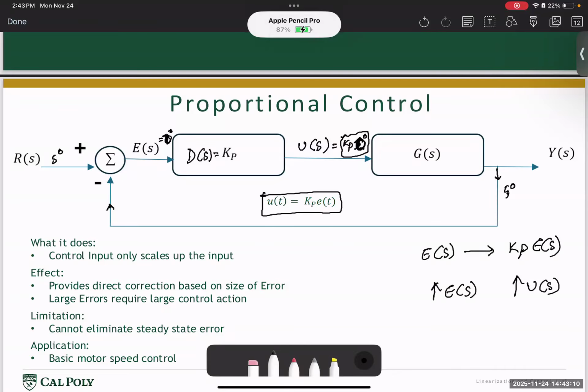This is sometimes undesired. Let's say you're using it for aircraft pitch control, and you provide a pitch of 5 degrees, but your aircraft only generated a pitch of about 1 degree. Then the difference between them is 4 degrees, right? Now this 4 degrees gets multiplied by a constant Kp, which usually is a very large value, sometimes of the order of 1e6 or 1e5. Then a large amount of control signal enters your system, causing large deflections on your ailerons.